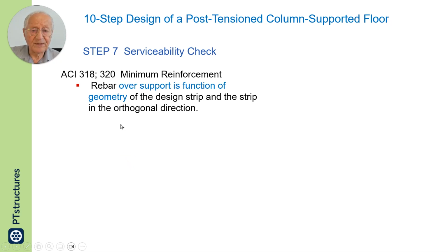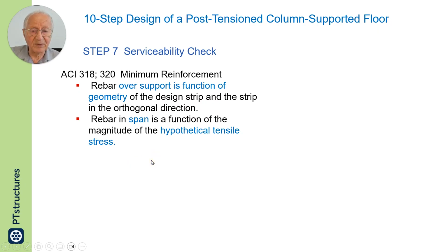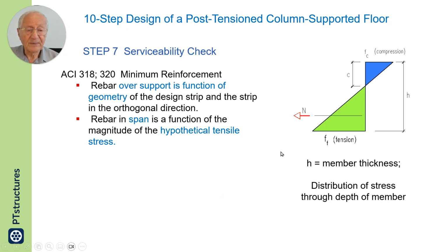Rebar over the support is a function of the geometry that I explained before. In the span, it is a function of the hypothetical tensile stress. You calculate the tensile stress at the bottom of the span, at extreme fiber at midspan, and depending on the magnitude of the tension stress, you may or you may not need bonded reinforcement. What I have shown here is the section at mid depth.